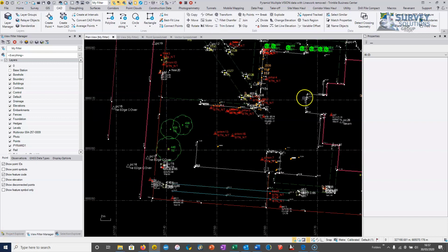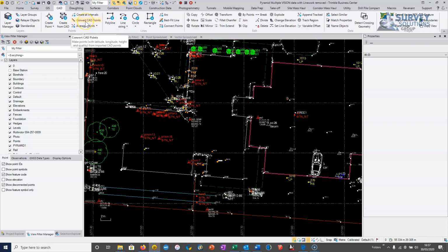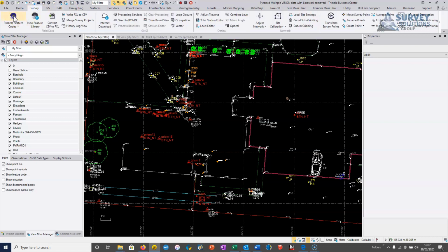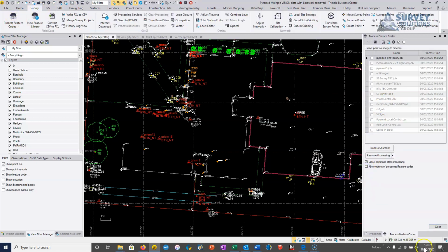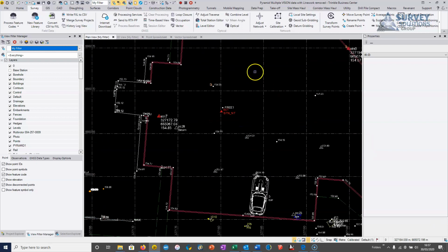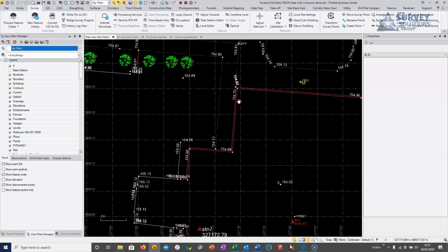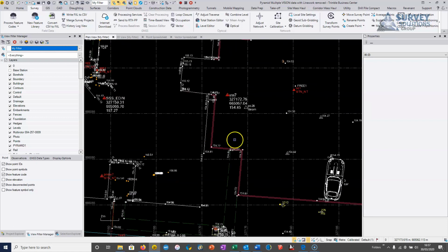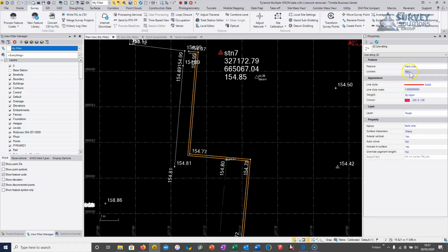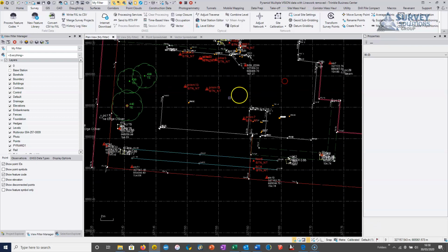Once we've made these edits in the database, what we generally want to do is stop any changes with codes having a knock-on effect. So we can lock things down. We can go back to our survey process feature codes, and say allow editing of feature codes to be changed here. If I untick that, when I make changes and hit F4, it's not going to put things back in place after I've made an edit. So you can lock things down, or you can even lock things down on an individual basis by going into an individual line and saying, don't allow any feature code changes to have a knock-on effect to that line. So we can lock things down on lines as well.